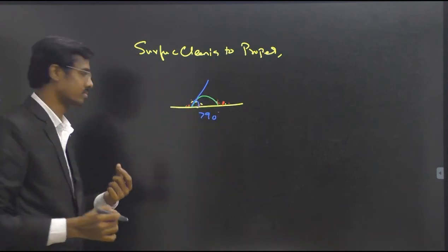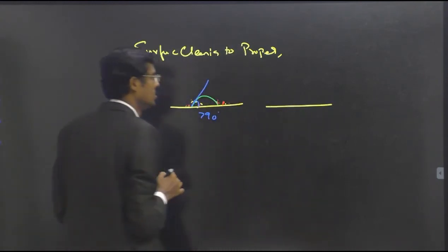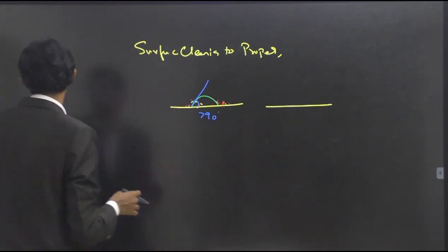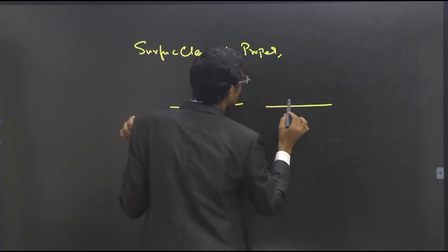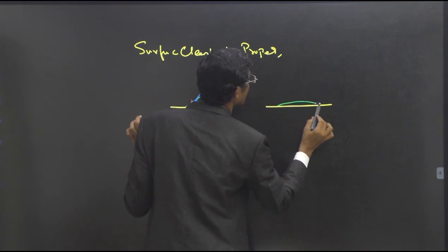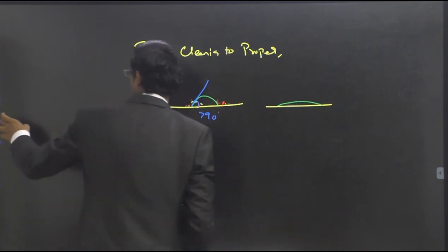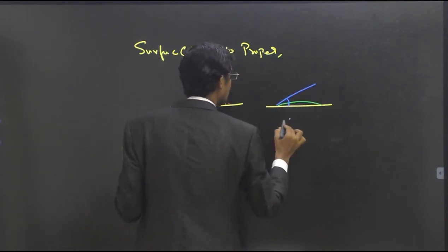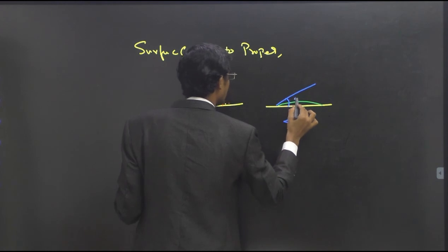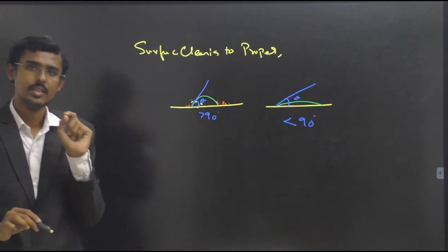But the same thing, when I am doing the cleaning process, I have cleaned now. No impurities are there. Now what happens when the liquid material is dropped? It is easily flowing over there. Therefore, what happens to the contact angle? The contact angle will be less than 90 degrees. Okay, so this we have to maintain.